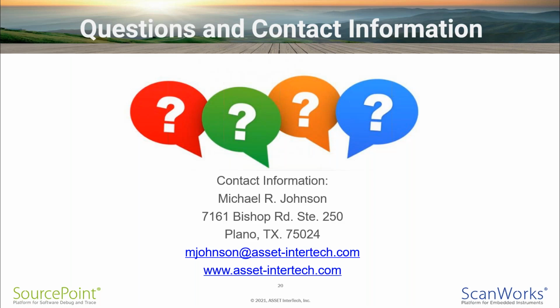Our first question, Michael, is you say that component action provides a level of functional testing capability. Does that mean it is running at board speeds? That's a great question, Alan. Since we are using the existing boundary scan infrastructure, we're actually running at boundary scan speed, or whatever you have your test clock speed set at.